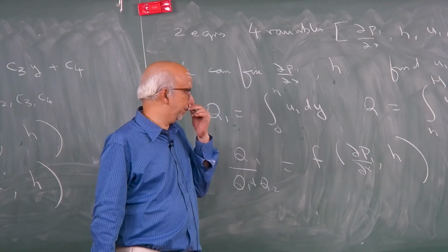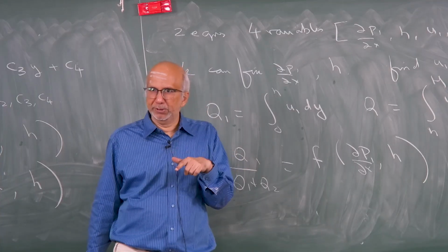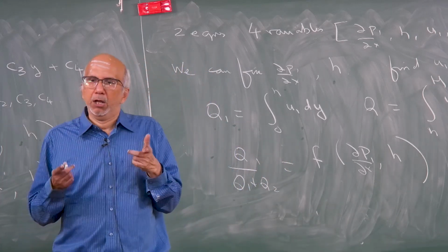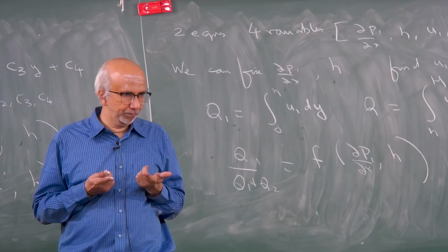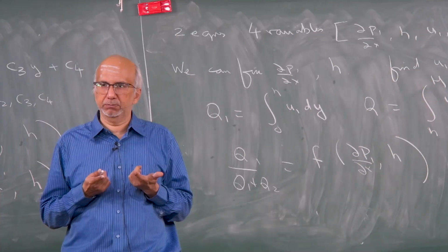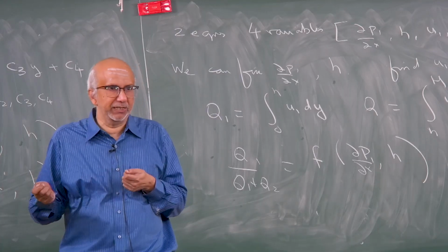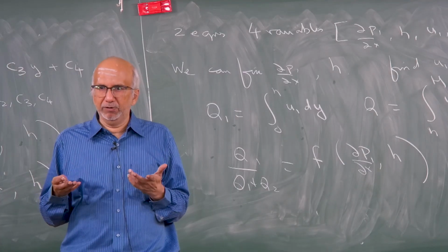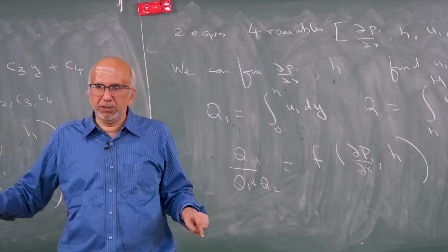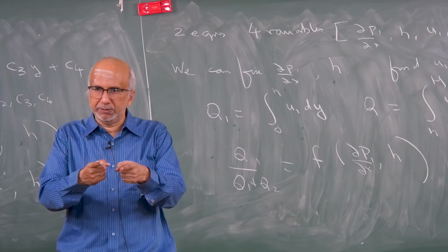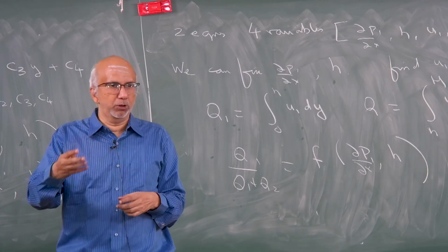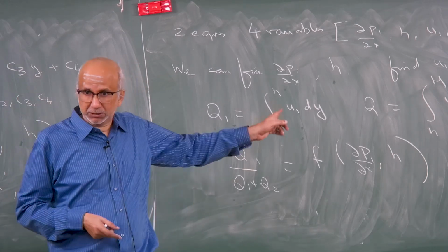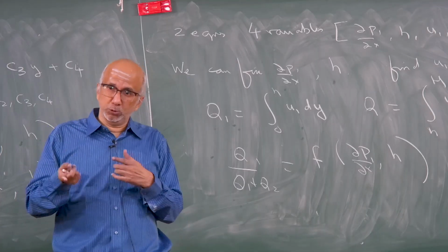So, the other thing you can do is, mathematically this is easy to do, but experimentally you are possibly going to be pumping in 2 fluids with specific flow rates. I mean, you are not going to keep doing an experiment to fix the h. H will be a dependent variable. The hold up, the interface position, is going to be a dependent variable. When you do an experiment, you will just turn on this pump, turn on that pump, the pumps will pump the 2 liquids inside, right. H is going to be found out, H is not known. So, from the mathematical point of view, this is the way to do. From an experimental point of view, you have to do the opposite.